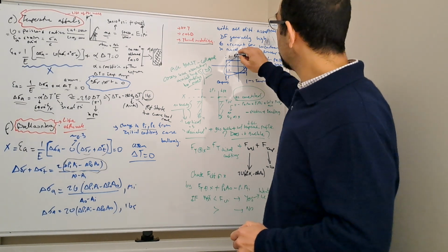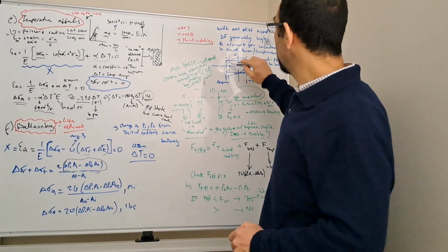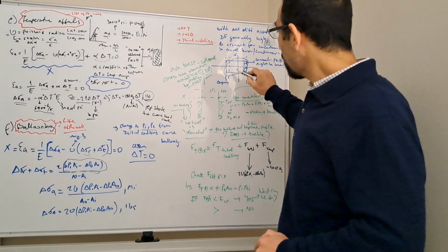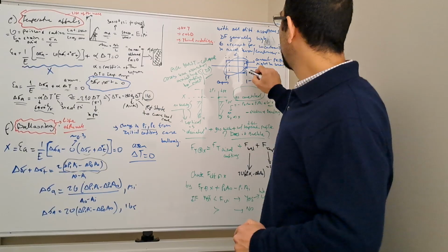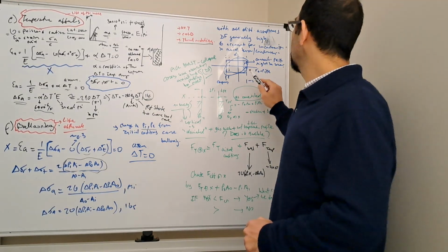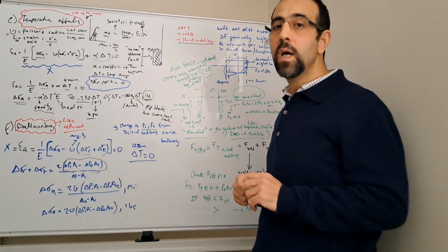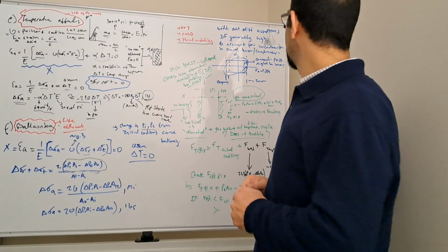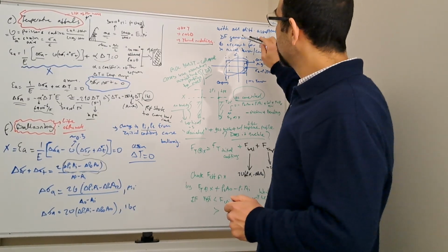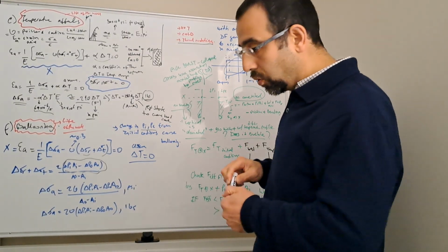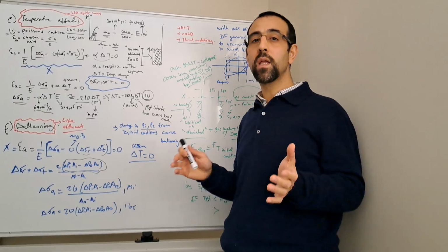Okay, and then let's talk about this part. The poorer or lower compression or tension limit for the pipe was discussed on the first page, where there's a special clearance requirement. Usually, as I mentioned, there is no difference in performance rating for burst or collapse. However, there is for compression and tension for the special clearance pipe. What they say here is what we can write to answer our question on the first page: why is the design factor for tension generally higher than for burst and collapse?